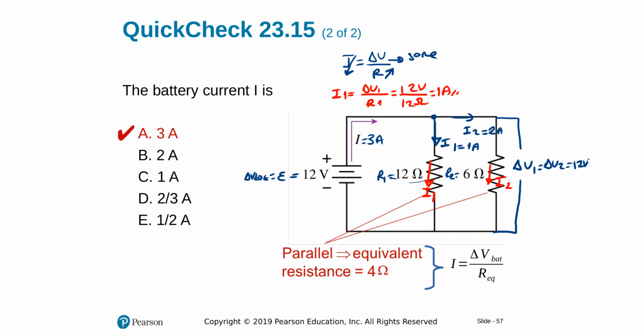I can go logical, divide my current, again twice the resistance, half the current's inversely proportional. I can use that. Or if I can't see that, I can say they have the same potential differences, define that 12 volt in this case, and use Ohm's law individually to get to the currents.